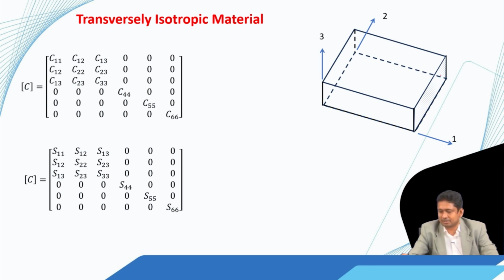So, let us suppose that this is our composite material, and at this face if I look at the fiber cross sections, their arrangement is regular. So, with a regular arrangement of fiber cross section, we can see same configuration in whatever direction we look. So, that makes it isotropic. However, if the fiber directions are irregular, then it is not isotropic. So, a composite with regular fiber arrangement has transverse isotropy in one plane.